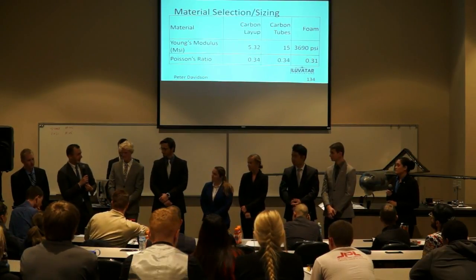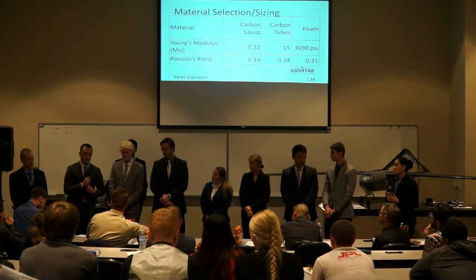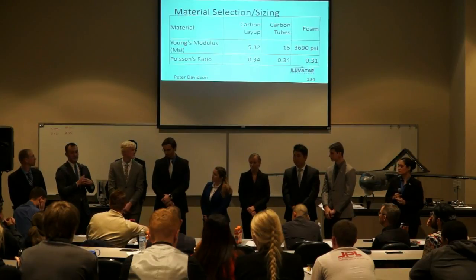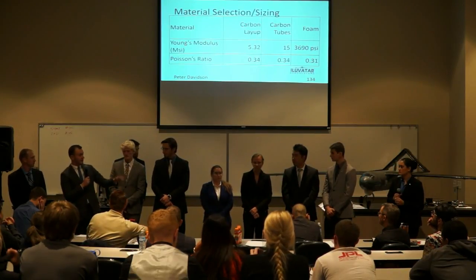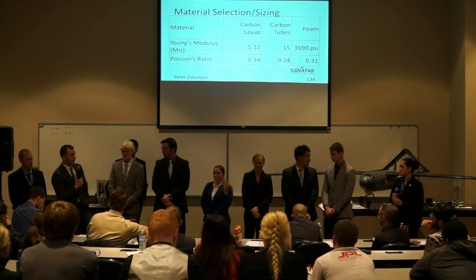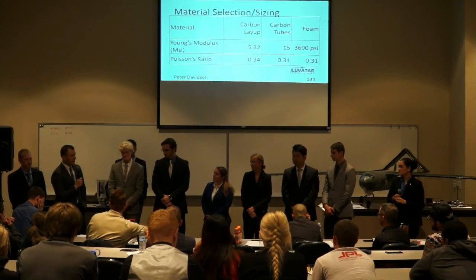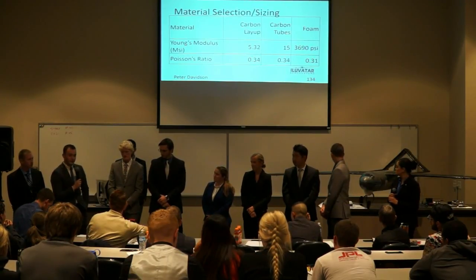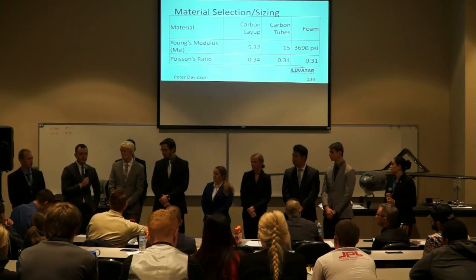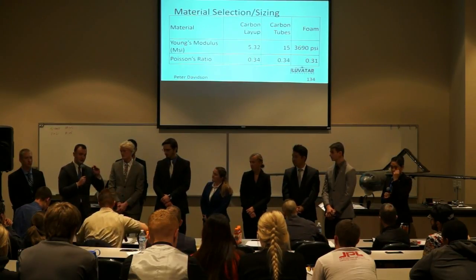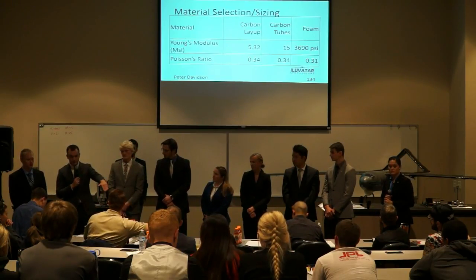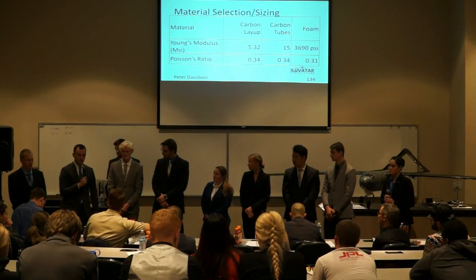So there were several things in the model that were predictable. First structure tested, we even had the foam support underneath it, and it was really bad then. We added that in first to help alleviate some of it. Then if you look at the photo of the actual structural testing, there's a lot of deflection happening. There's a discontinuity in the curve, it's deflecting right at that first disconnect point.